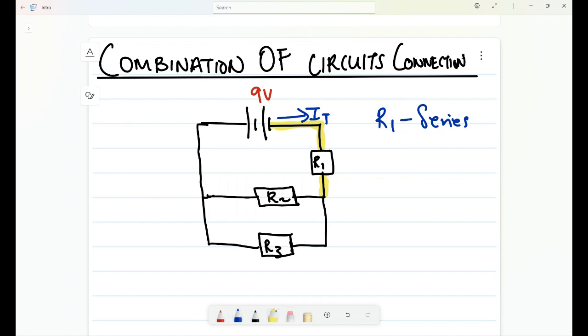Now, can you see, when I reach this point, my voltage wants to divide. The other one wants to take this route. The other one wants to take this route. Now, what does this tell me? This tells me now that R2 and R3 are in parallel. Why? Because now they cause the total current thereof to split. When I reach here, I'm still talking about the I total, but immediately when I get to this point, I'll have I1 and I'll have what here? I'll have I2.